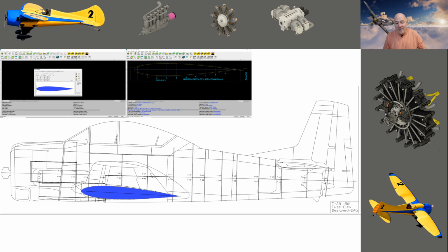How do I say this right? When you've got a flat bottom wing, the faster you go, the more lift you're going to get. A fully symmetrical wing that has a 3 degrees up incidence, if you get that down to about a ½ degree incidence and go fast, it doesn't want to keep climbing. You've got a lot better ability to go fast without it always wanting to climb, you always trimming the nose down. So that's one reason on this I'm using a fully symmetrical wing, because when I go fast, I won't have to use so much energy or forces to keep the nose down and go fast, if that makes sense.